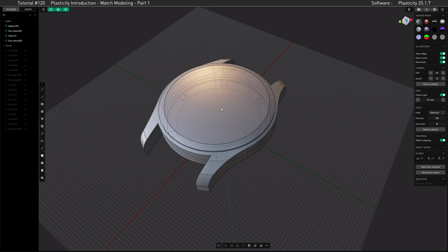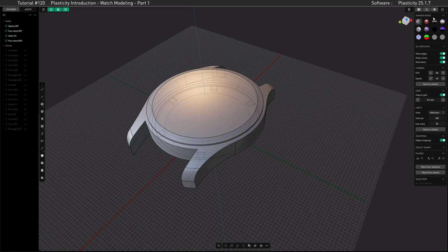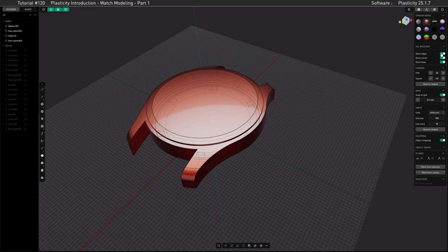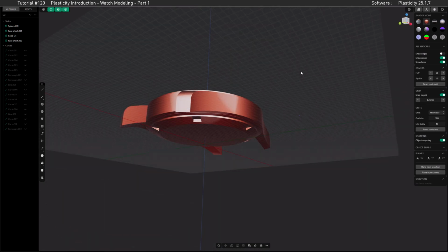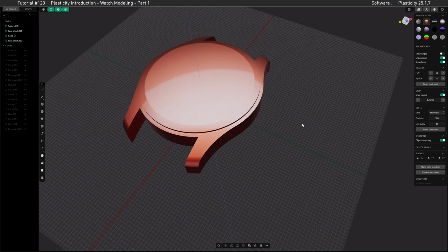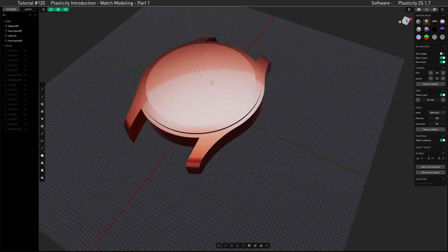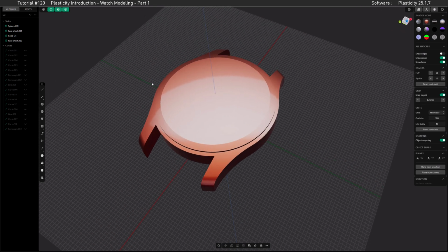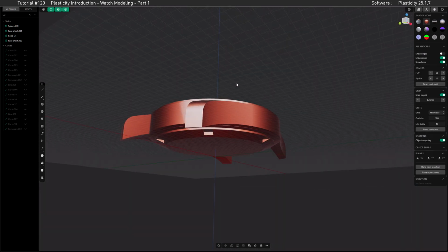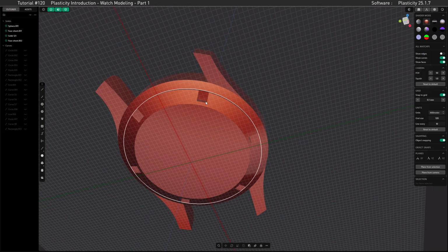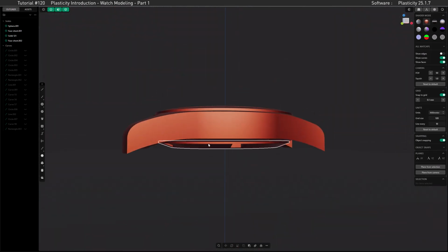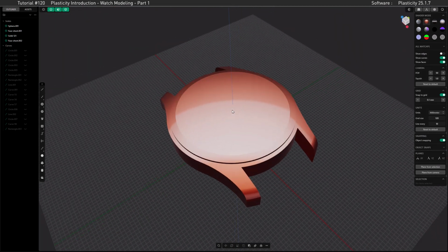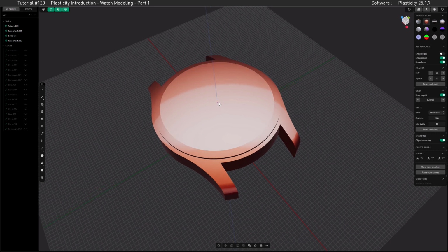If you want to marvel at your creation, what we can do is go to the shader mode and choose another matte cap, and also get rid of the show edges, and therefore you can see the object in its full glory. Now you might wonder why there's no filleted edges on there. The reason is rather simple. Modeling operations, as we did in the backside here, wouldn't be possible if we had rounded those edges before. So the most valid workflow for me is to finalize the object completely, then duplicate it, and then have a version with filleted edges.